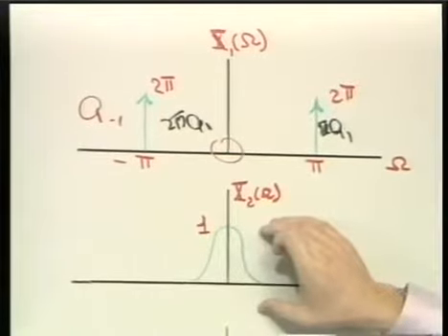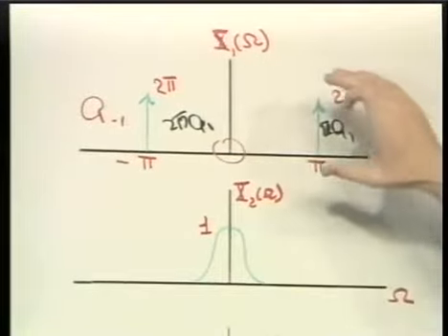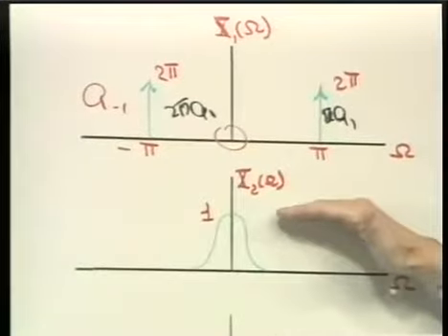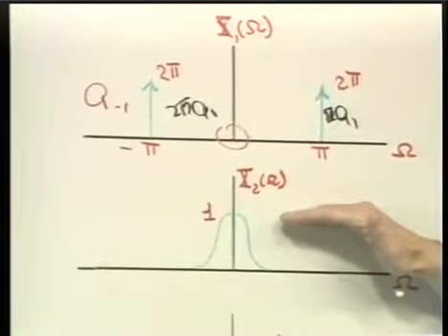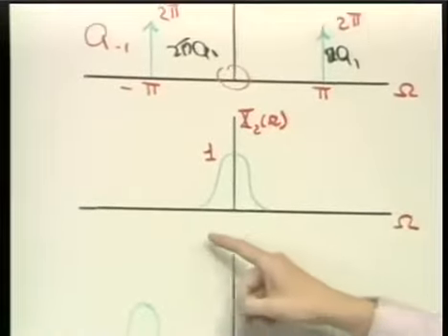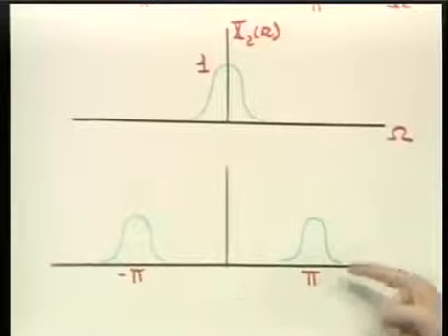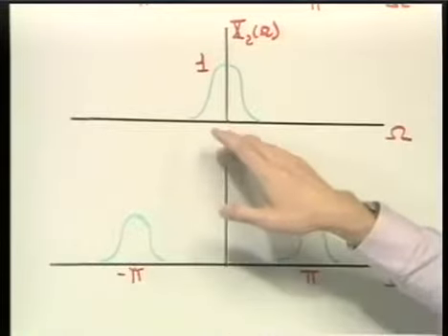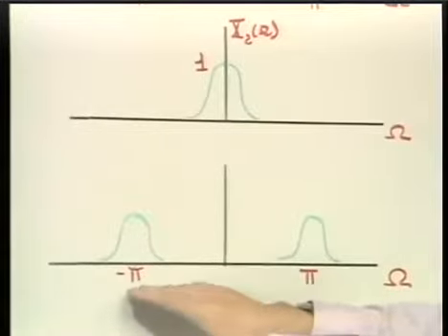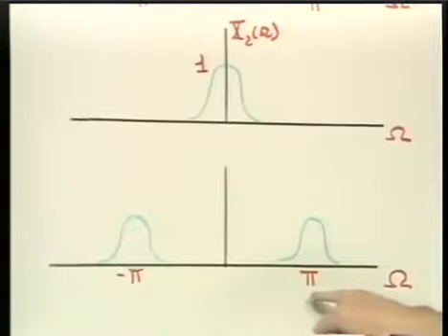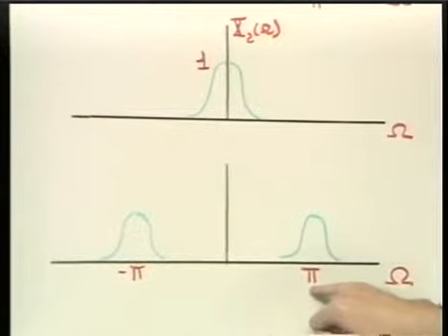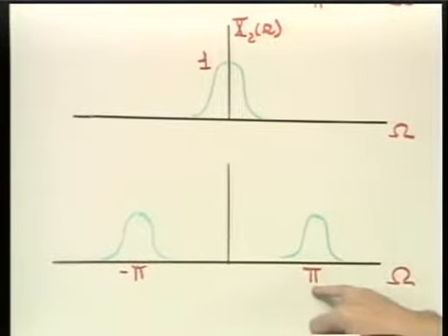And recall that if you convolve something with an impulse train, as this is, that simply corresponds to taking the something and placing it at the positions of each of the impulses. So in fact, the result of the convolution of this with this would then be the spectrum that I indicate here, namely this spectrum shifted up to pi, and of course to minus pi, and then not only pi, but 3 pi and 5 pi, et cetera.